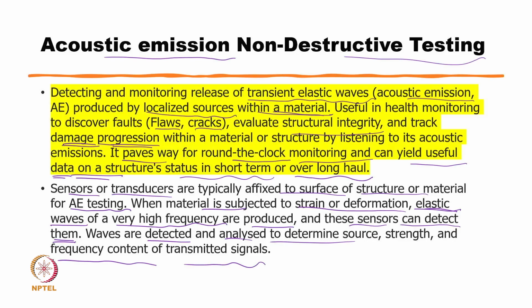As I mentioned, we need to have a database to say, okay, maybe 10 Hz frequency means what, this much amplitude means what, if the amplitude increases what kind of fault will be there. Or maybe we are continuously doing a time analysis, then we can say, yeah, initially the crack was this much smaller, now the crack is continuously increasing, and then we need to give a signal for the overhauling or the maintenance.